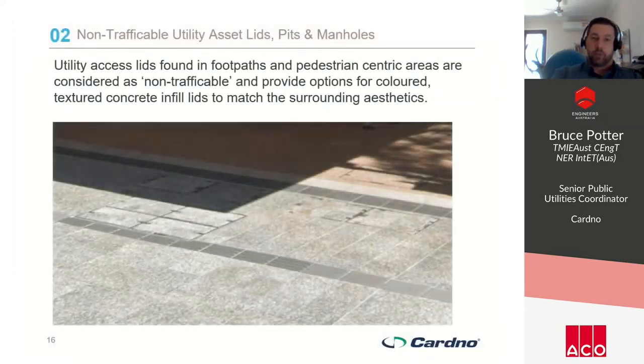Non-trafficable assets are normally found in footpaths and pedestrian-centric areas. With these, they have the benefit of interchangeable pit lids, which can be matched to the surrounding aesthetics, and they can be coloured infill concrete lids. So rather than having your standard lid that the asset owners may have, which is generally a cast iron lid, they can be interchanged, and as you can see there, they can match in with the aesthetics of the surrounding area.